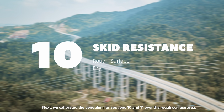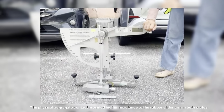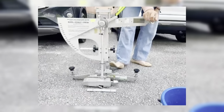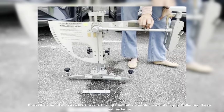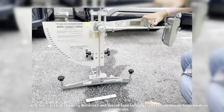Next, we calibrated the pendulum for sections 10 and 11 over the rough surface area. The physical aggregate contact provided higher resistance to the rubber slider arm in both states. Even when wet, the coarse texture cuts through the thin water film to maintain grip. Collecting this value helps engineers predict stopping distance and overall road safety parameters across variable weather conditions.